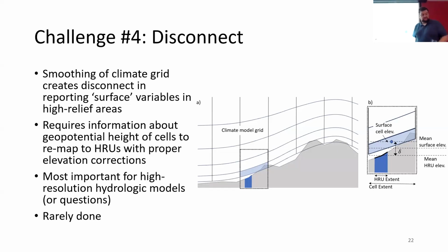And then what will be the impact of not doing that exactly? So for instance, if the climate model is overestimating its elevation, it's going to assume a colder temperature than is actually present at that location. And these differences are not small, they can be 200 meters off in BC. And 200 meters is the difference of having a meter of snow on the ground and having no snow on the ground in some cases, which is especially important to the Rockies.